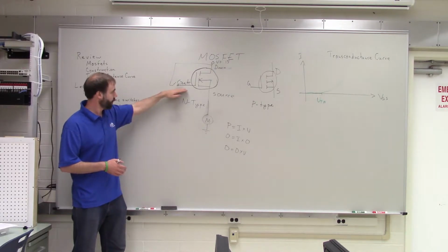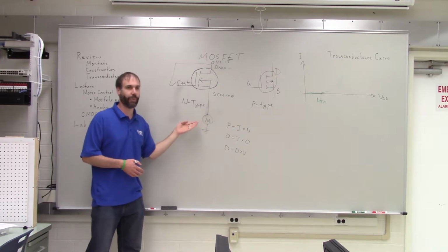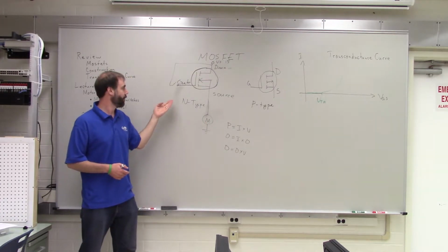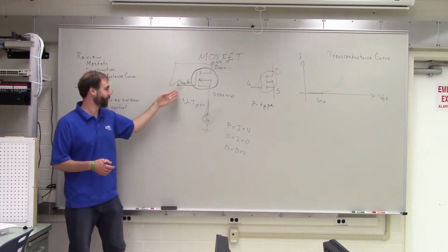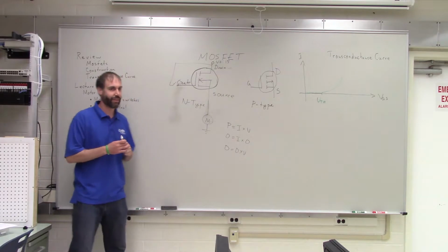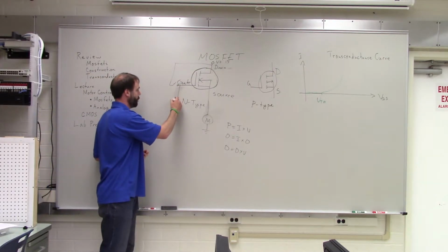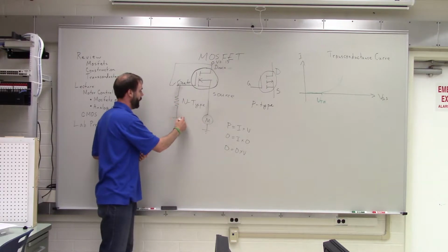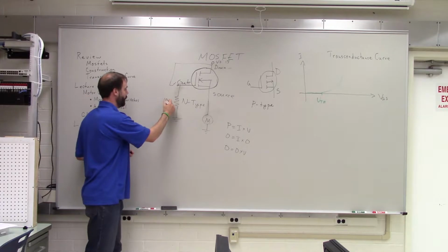Now imagine that this voltage is controlling the current going through a big motor. So when somebody walks by, the motor turns on. When somebody else walks by, the motor turns off. This is not a good place to be, right? So what we need is we need to have this resistor here, okay? So this is usually a high value resistor, like 10 kiloohms or something.